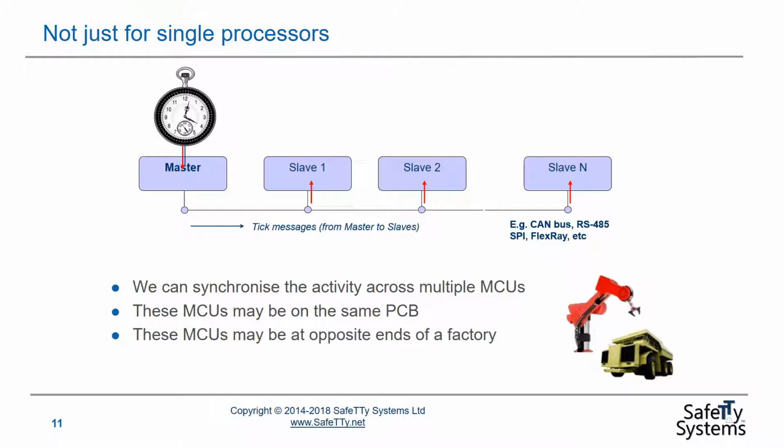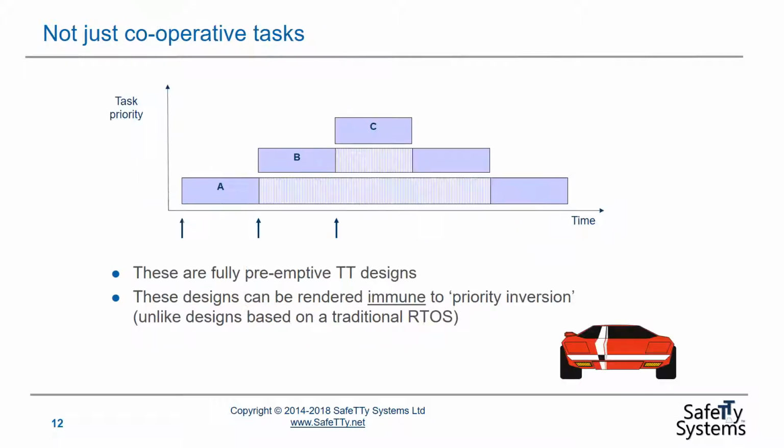These microcontrollers that we're synchronizing the activity on, they may be on the same PCB, or they may be at opposite ends of a factory or in different parts of a vehicle, for example. It doesn't greatly matter. We can synchronize the activity across multiple processors very easily using this kind of time-triggered design.